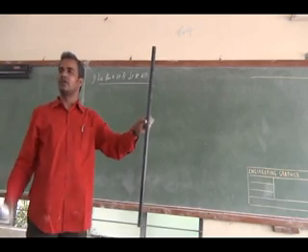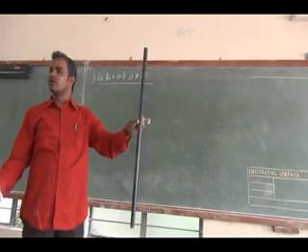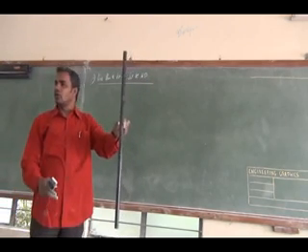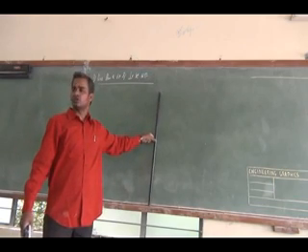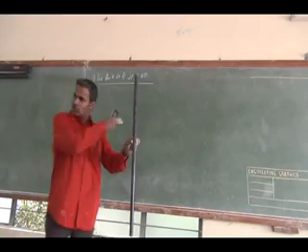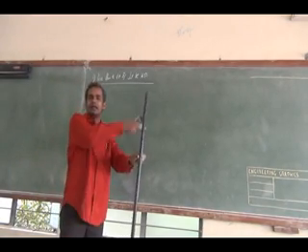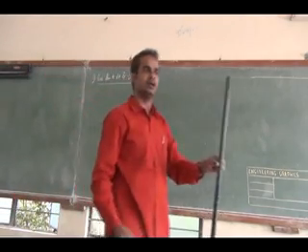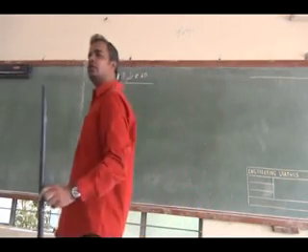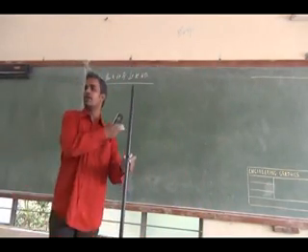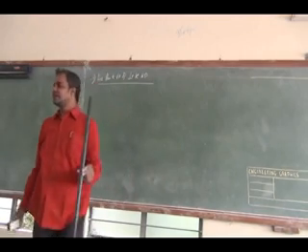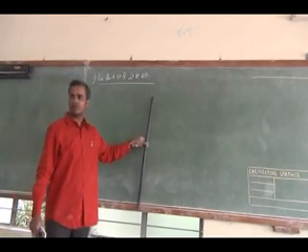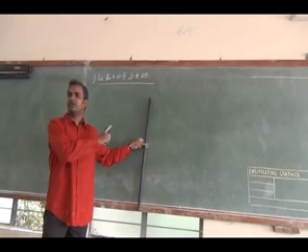The front view length of the straight line will be 50 mm. Why is it the same length on the front view? Since it is parallel. If a line is parallel to any one of the planes, I will obtain the true length of the line, that is the true dimension of that line in that plane. Since the line is parallel to VP, the true length will be obtained in VP. In VP I will have the front view.